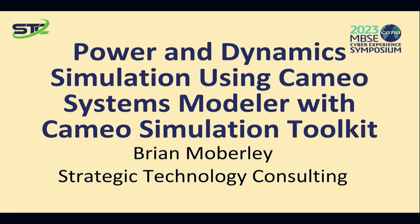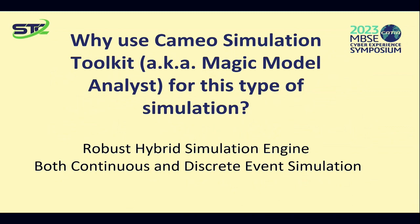I know a lot of people, when they talk about dynamic simulations and simulating power, immediately start thinking about MATLAB and Simulink and doing those types of simulations in those environments. What I'm hoping is that you'll see that it is also possible to do that directly in Cameo Systems Modeler without MATLAB and Simulink, because Cameo Simulation Toolkit does have a robust simulation engine, and it is both a discrete event simulator as well as a continuous simulator.